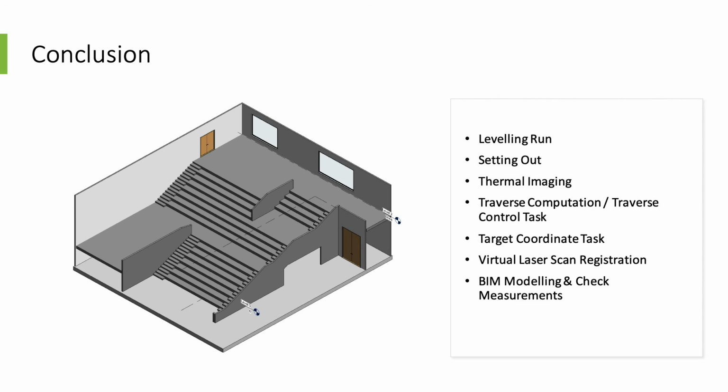In conclusion, the heights of the 2nd floor in the Here East auditorium were computed using the rise and fall method, which has been thoroughly explained. The calculations were all double-checked to make sure that the final result can be used in further tasks such as modeling the auditorium. For the setting out task, distances measured by the surveyors using the equipment were checked with the calculations to compare the differences and evaluate potential sources of error and uncertainty. There were no major uncertainties or errors found.